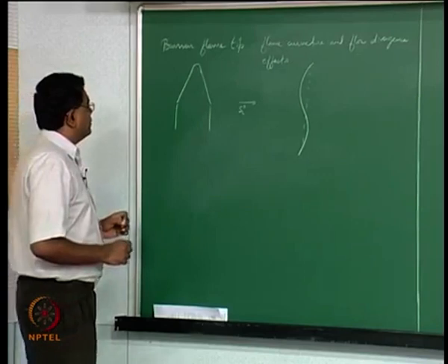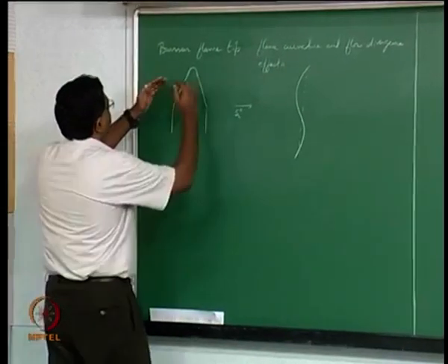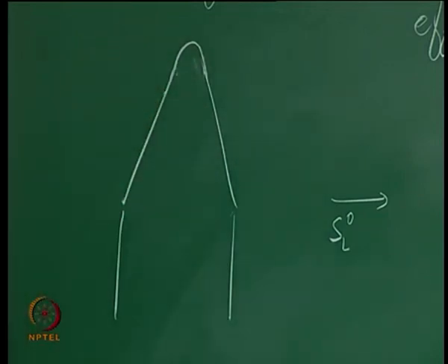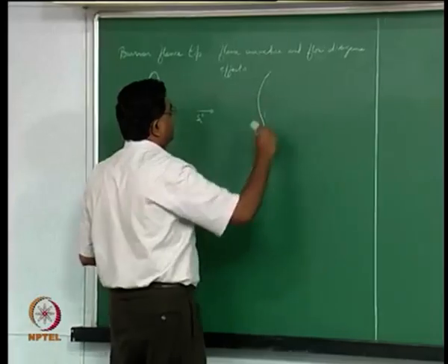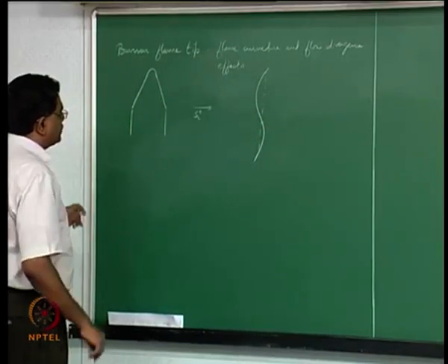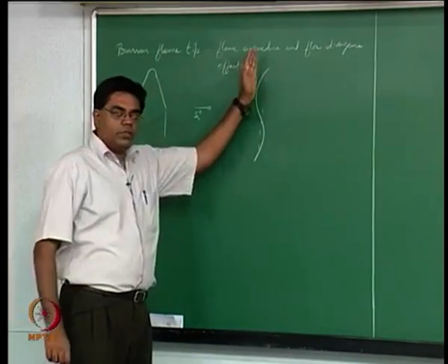What we find is we now have to think about a locally highly curved flame there, and see what happens when you have a flame that is so curved. Therefore what we want to do is think about flame curvature, and also another aspect we need to worry about called the flow divergence effect, in the context of a small perturbation to a plane flame.